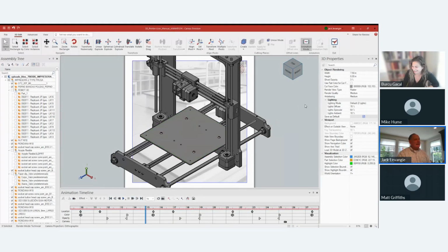So this is in edit mode. As you can see from the contextual tab, you have the 3D edit mode. This means that I am inside, because you can see the assembly tree and everything. However, you see this is selected, I am in animation mode. I'm going to hide that so that you have a better chance of seeing what we need to see. In animation, everything is done with your parts and how you want to project them. And it's all done with the idea of keyframes.